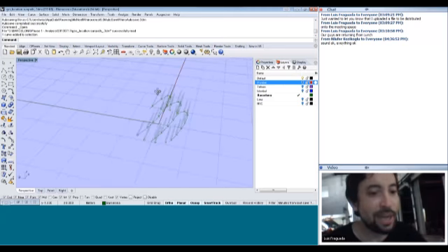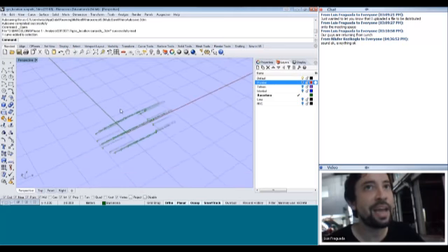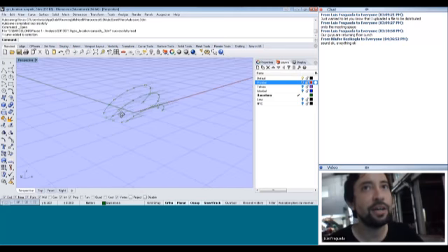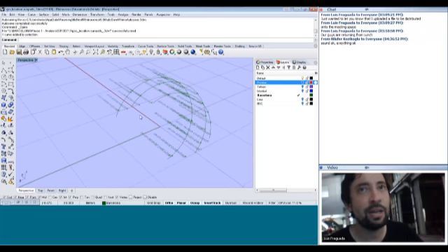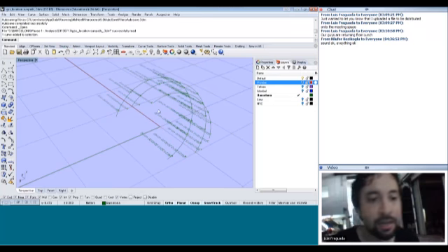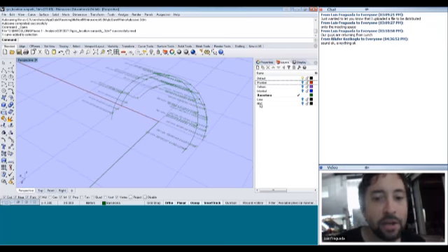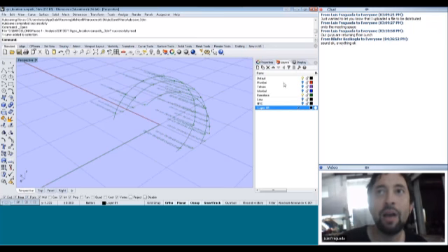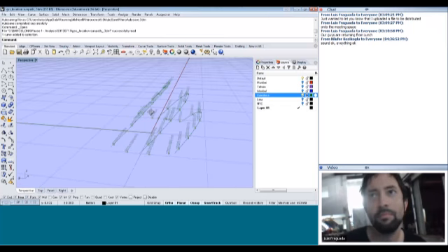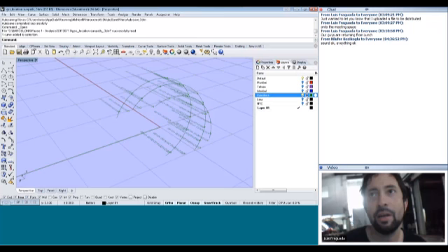So the first thing I want to do is make a fake sort of plaza here, a fake set of buildings, and just try to understand how we could use this information to see the radiation on the surface of an open space, a public space. Okay. In a new layer in Rhino, and actually I'm going to lock the Barcelona layer, so I can't select anything now. So I lock the layer by clicking on this little lock over here.